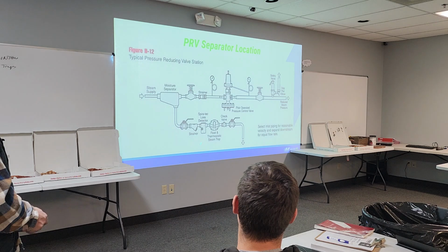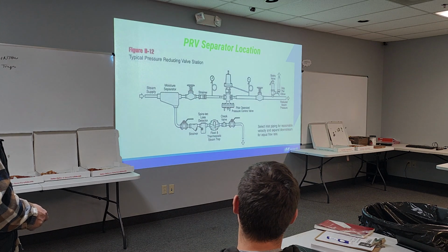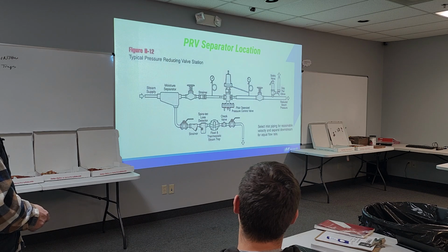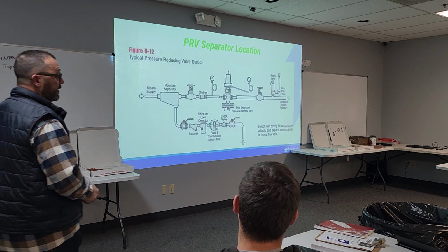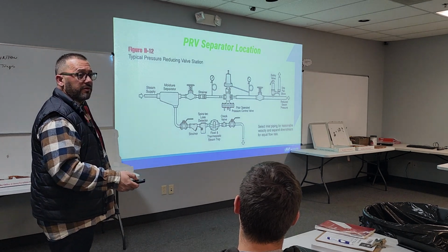Again, we could use a TD trap here. The nice thing about the float and thermostatic traps, which we're going to get into real quick, is that they will basically handle the condensate as rapidly as it's formed.